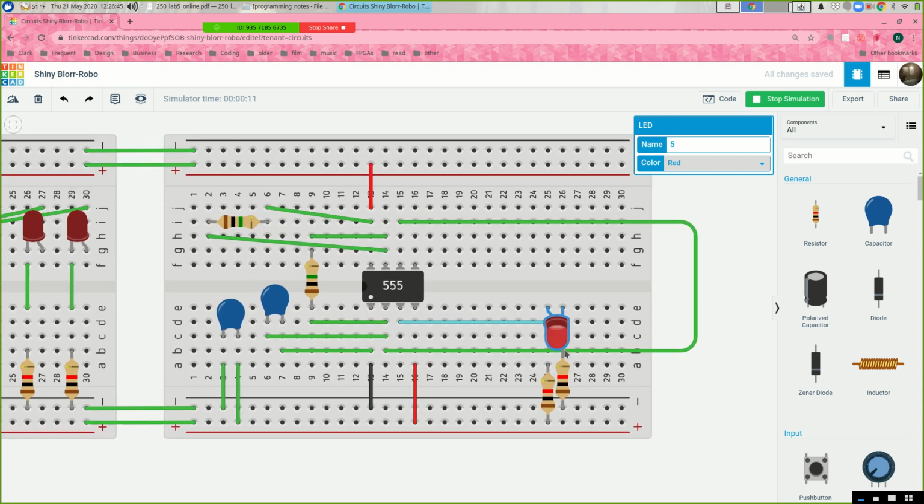It's on for about 1.5 seconds, and it's off for about half a second. Okay, that's the behavior you want out of this device. With those values of the capacitor and the 2 resistors, 1 microfarad, and each of those 1 mega ohm, this should blink at about this speed. And if your LED isn't blinking, then there's probably a wiring issue somewhere.